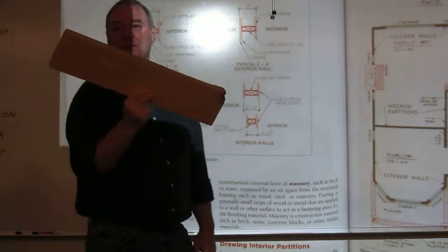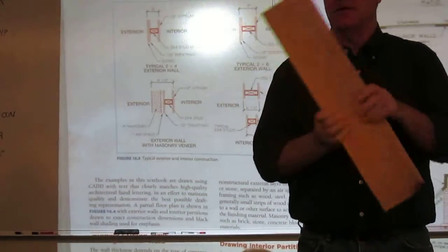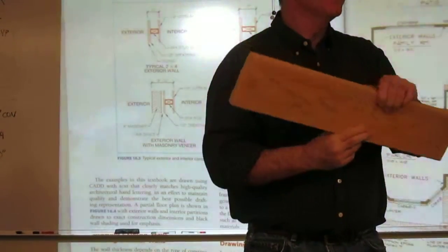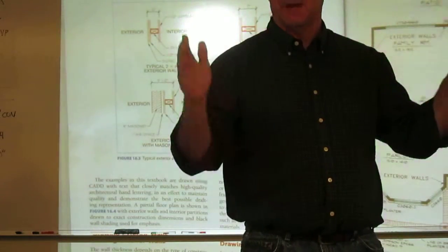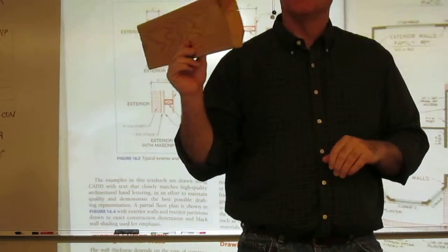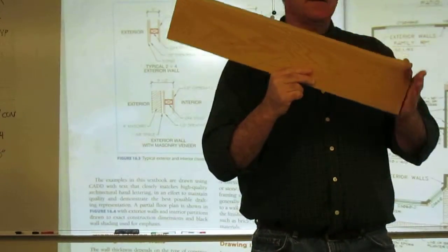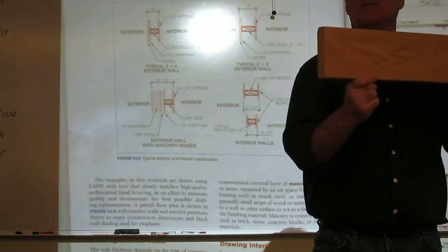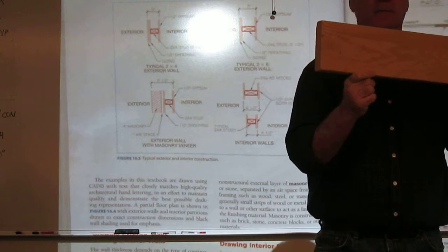Typically with what we call nominal lumber. By nominal lumber, I mean a 2x2 or a European stud. 2x4, we don't use much 2x2s around here. 2x4, 2x6, 2x8, 2x10, 2x12. Those are my nominal lumber sizes. You've probably all heard those terms. Subtract a 1/2 inch from the dimension and you have the actual size. So this is a 2x6. If I'm going to subtract a 1/2 inch, what size is it really? It's 1.5 inches by 5.5.